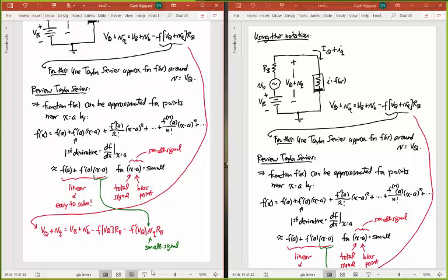Okay, so I've set the whole thing up now, and what this really is now is two problems in one. This is like two problems superimposed. It's like a large signal DC problem, which we're going to have to solve just like we just solved that MOS biasing problem. But it also includes, with the little v terms, a small signal problem that actually governs all of the amplifier characteristics in the end. And you can see that's a linear problem. You may not be able to see it yet, but in the next lecture, I'm going to separate these two into two problems. And determining the amplifier performance is going to be basically solving linear equations.